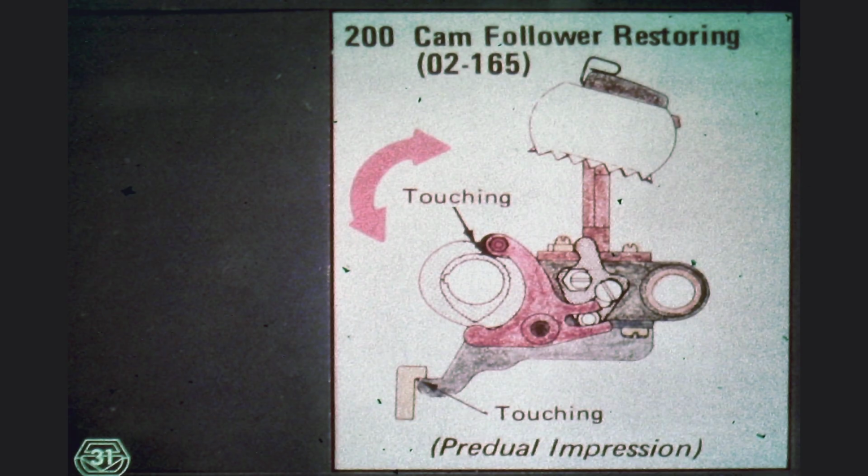This drawing also shows us the adjustment of the restoring roller on the print cam follower. Notice that when the extension underneath the rocker touches against the lower surface of the horizontal portion of the anvil, the rocker restoring roller should be touching the cam. Since the anvil adjustment no longer exists on dual impression machines, we do not have to worry about it when we adjust the carrier support rail. But on pre-dual impression machines, the rail is mounted according to the position of the platen. With the multiple copy lever on 5, no printing of the period. With the lever on 4, light printing of the period.